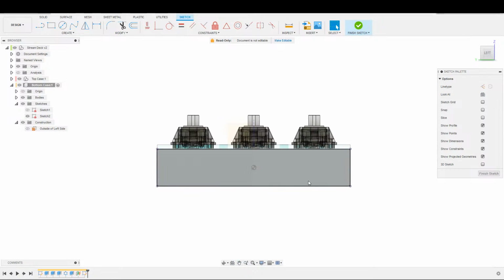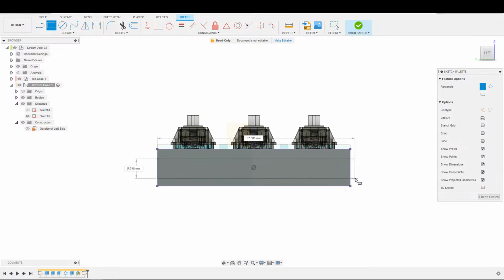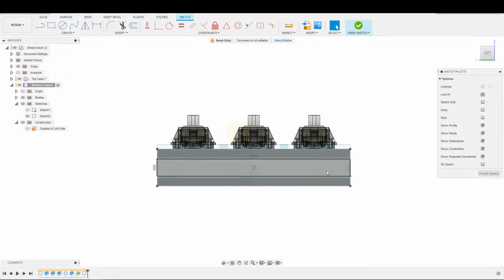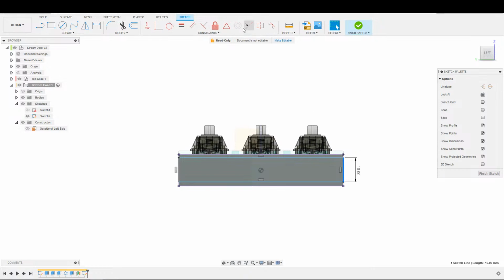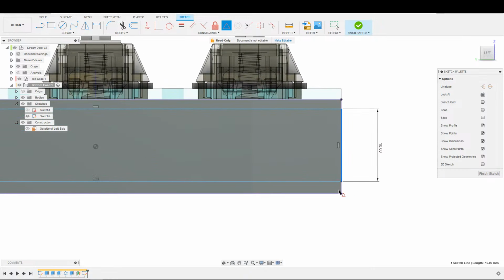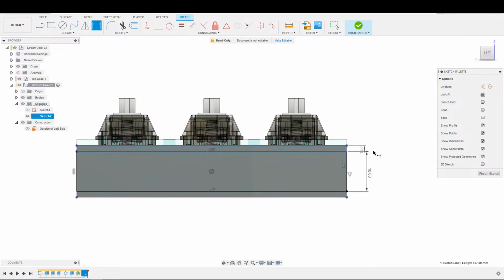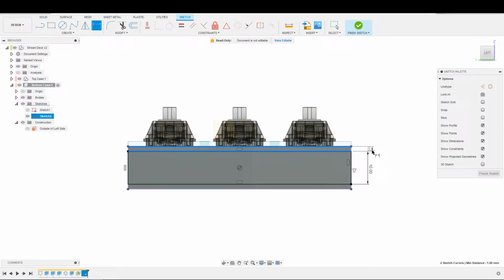Again, I'm trying to keep this pretty simple here. One thing that I did not consider is I said that the 623s are smaller than the switches. They're smaller than the bottom half of the switches even, but I forget what the outside diameter is. I think it's, okay, it is 10 millimeters for the outside diameter. So let's draw that in here really quick. So there's our 10 millimeters. And if we have that centered on here, I knew it was going to fit, but I wasn't sure how much meat we'd have on either side of it for the slots. And it looks like we have 1.5.